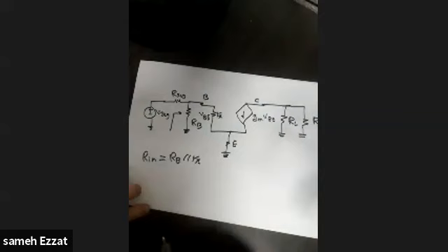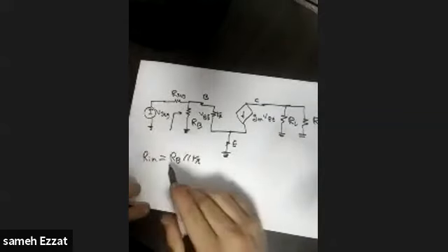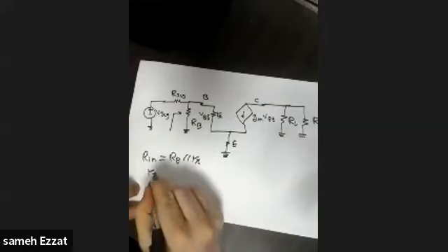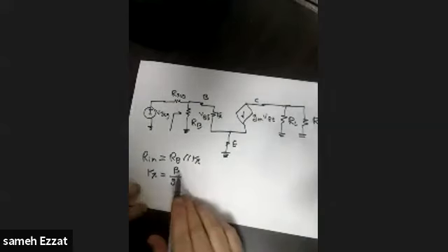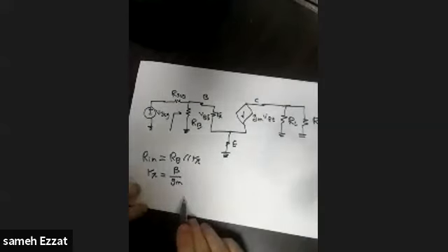So this is simply the input resistance. RB will be given, and R pi equals beta over GM. Okay, beta will be given in the body of the question. GM will be calculated in a few seconds. Please wait. So this is the R in, or the input resistance.